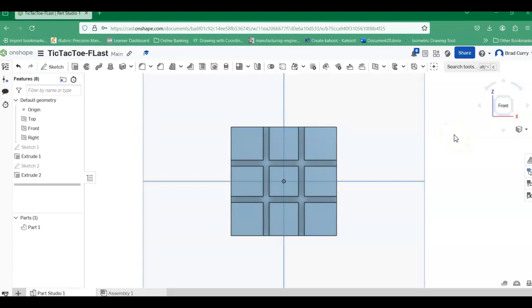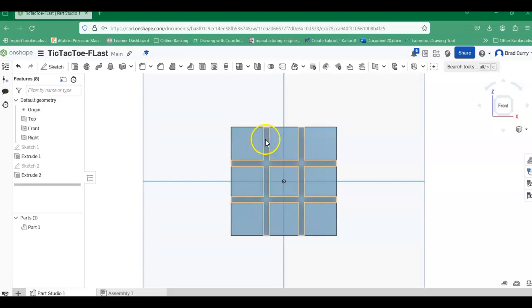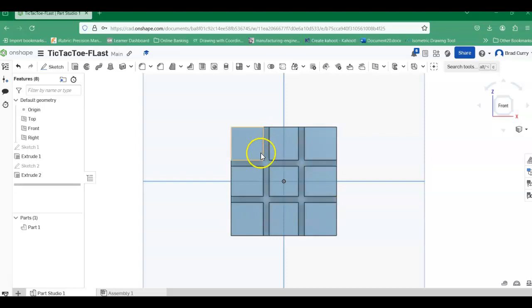All right, so we are ready for the center holes here, and we're going to have holes in the middle of each of these based on our geometry. And this is where we're going to need to make sure that we keep these in the right location. Because remember, right now, our center line is really the center of this slot here and not one of these lines. So if we just go picking off of these lines, the hole is actually going to be out of position. So we want to make sure that we are getting these in the correct position.